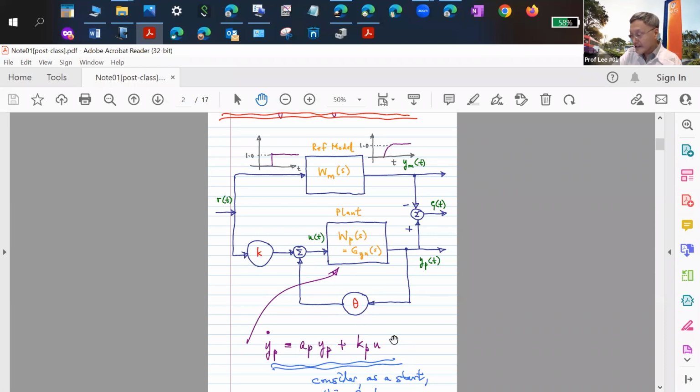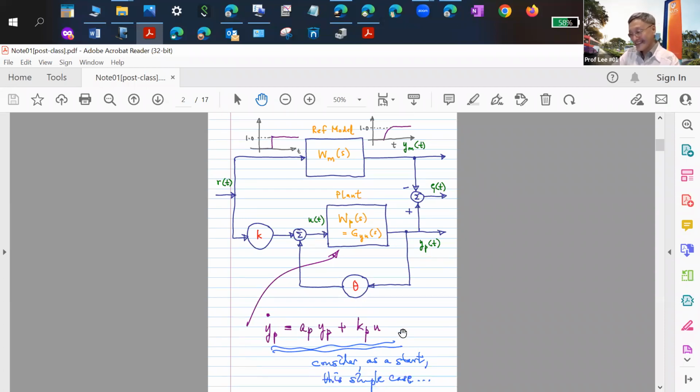So if you are given this system and you want to do this, even before doing adaptive control, you have to ask how might I even do this? Clearly for this simple system, I have the output measurement, I take it, multiply by a gain. Then I have my command reference signal. I multiply it by a scaling gain, put it in. This would be quite typical.